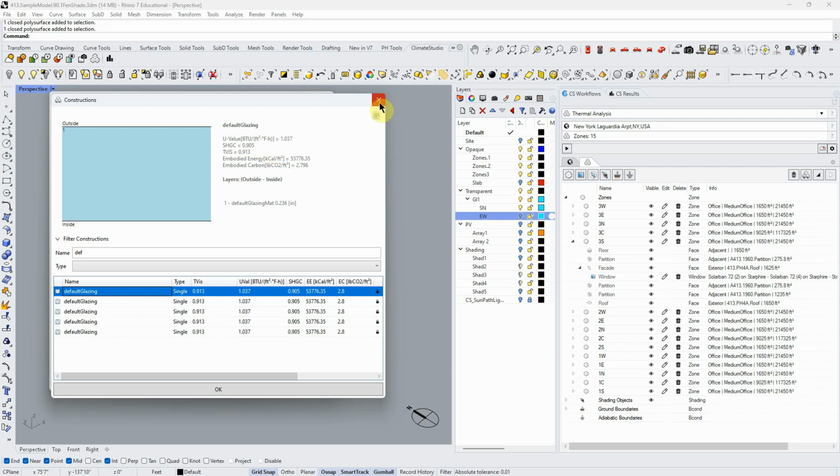When you're looking at the opaque, it's just going to be the reciprocal of this. A U value of 1 is really bad because that would be an R value of 1. And even a cheesy wood frame wall is going to have an R15 or something like that. So windows have very low resistance to heat flow.